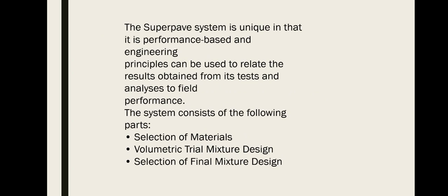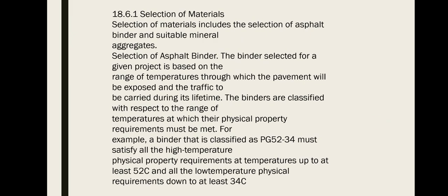The system consists of the following. First, the selection of materials. Second is the volumetric trial mixture design. Third is the selection of the final mixture design. So, the selection of materials. Selection of materials includes the selection of asphalt binder and suitable mineral aggregates.